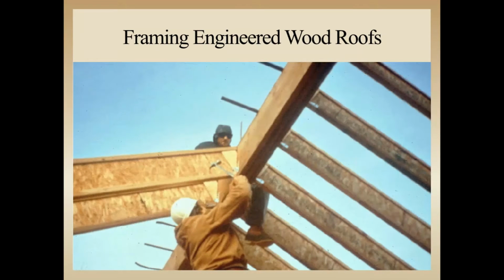In this picture, we see obviously a cold weather installation of the detail from the last slide. Note that the rafters along one side of the beam are already in place with straps ready to be bent into position and secured. When doing overhead work, it's often more convenient and safer to put the connectors in place on the ground. In this case, the sloped connector and wood stiffeners could be placed on the ends of the I-joist before lifting them into place. It's also possible that the flat strap could be pre-nailed to the joists on the right-hand side of this photo as well.